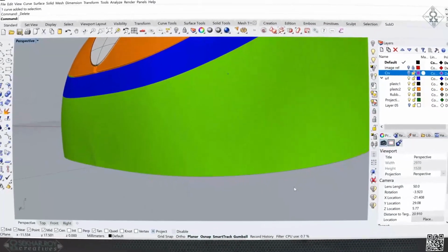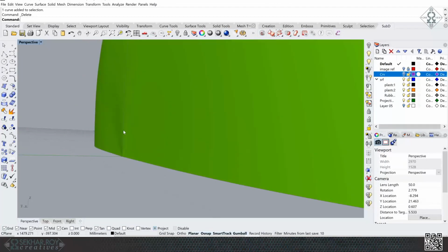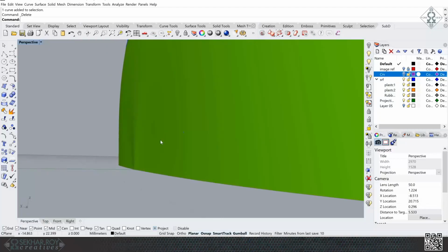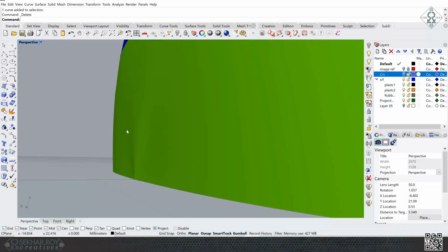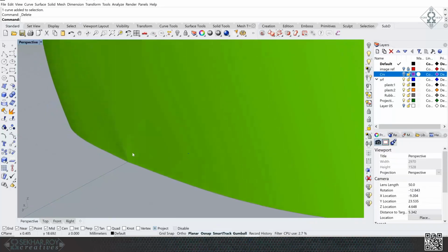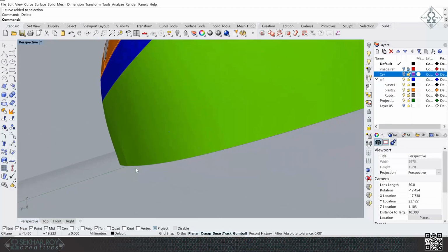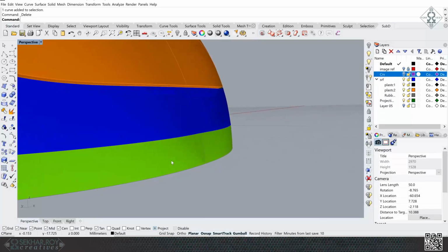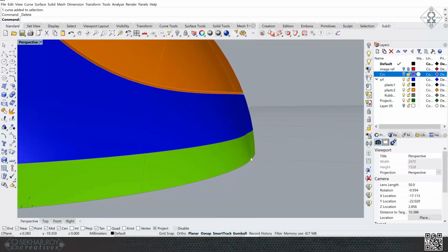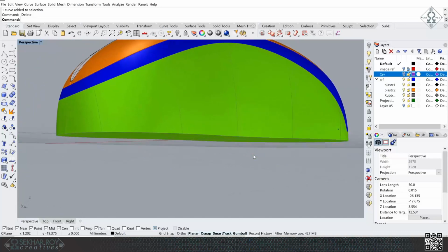So in this part, we're going to check how to fix this issue here. You can see the shading is slightly different here, how the shape is making a slight kink, and this kind of shading is not okay because fillets will always fail in these situations. If you try to do fillet here, you can see also in this part here, fillet will fail. Let's try the fillet just to see if it works or not.